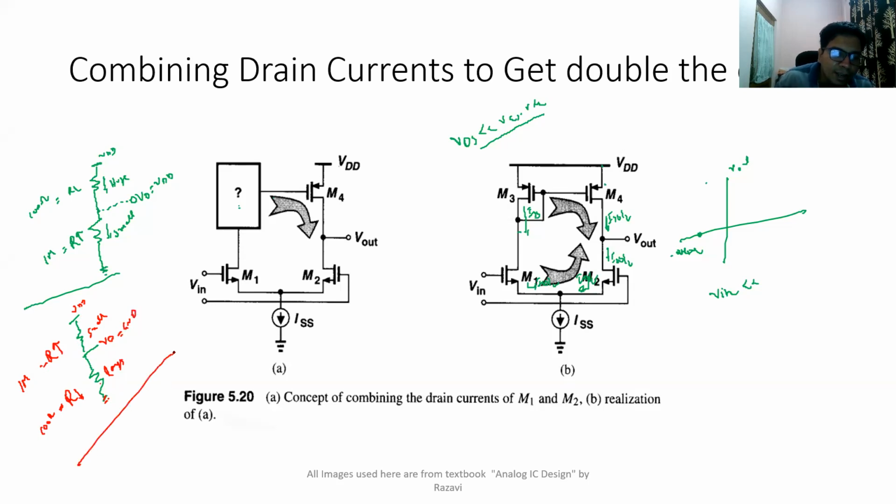Now imagine a third scenario where you assume two resistors, where some current X is flowing here, and the same current X is flowing through this other end. If X is flowing here and X is again flowing here, what will be the resistance of these two things? It is going to be the same, equivalent by 2, or RE by 2. And what is going to be V naught? Half of VDD, VDD by 2. So it is going to behave in the same way.